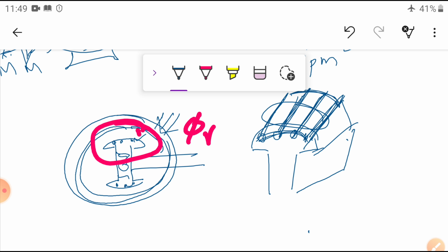Now what will happen? This is in a stationary position, this is in a rotating position. There is a high relative motion between the stator field and the rotor. Then, as per Faraday's law of electromagnetic induction, it induces current inside these damper windings. Once they are short-circuited at both ends, an EMF is induced in them and current flows.